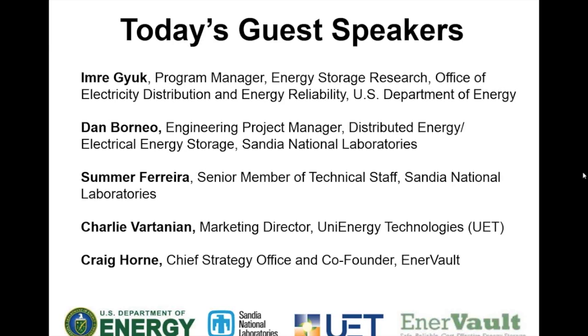Okay. Are they susceptible at all to overheating, or are there other issues that we should be aware of? Because of very large tank size, they're much less susceptible to overheating than any other battery type. You always have concerns in the power electronics, but in terms of the battery itself, that's an advantage of a flow battery. I think it's common to all flow batteries: if you stop the pumps, the reactions stop. And as Summer said, there's such massive thermal mass, usually in the electrolytes, that overheating is not an issue.